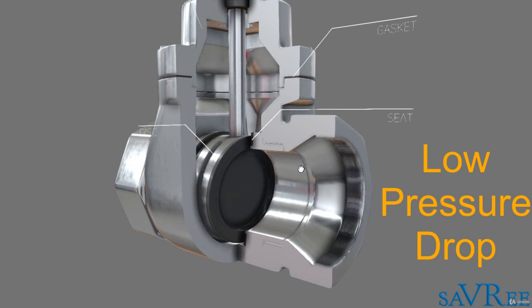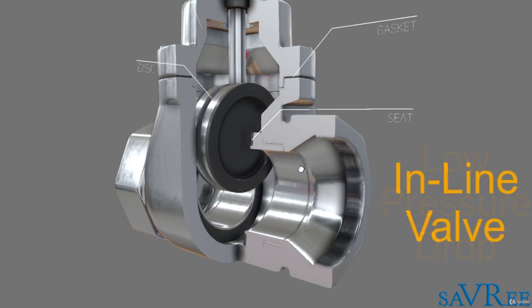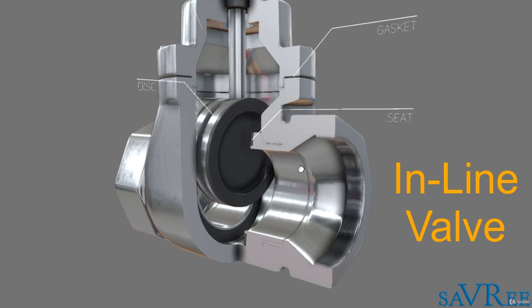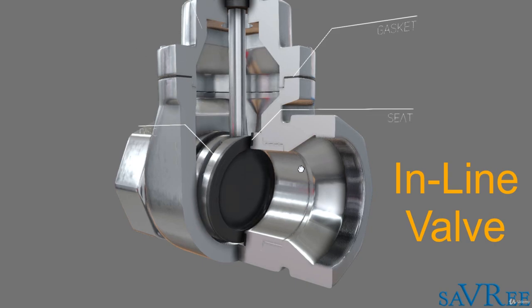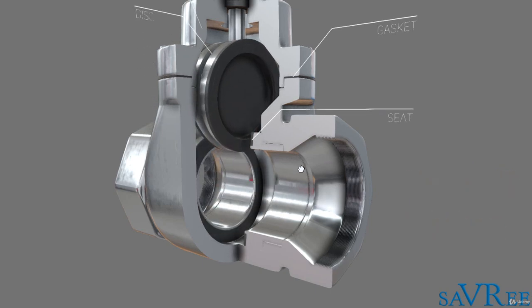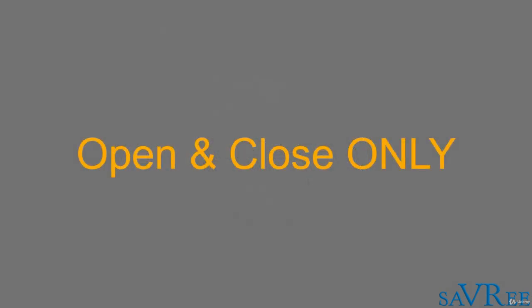Now gate valves are normally used in line. That means they're used just to pass flow through, but occasionally you might need to close the valve and isolate the system, and that is what a gate valve is for. Gate valves are only used for open and close. They're not used for throttling or regulating the flow.